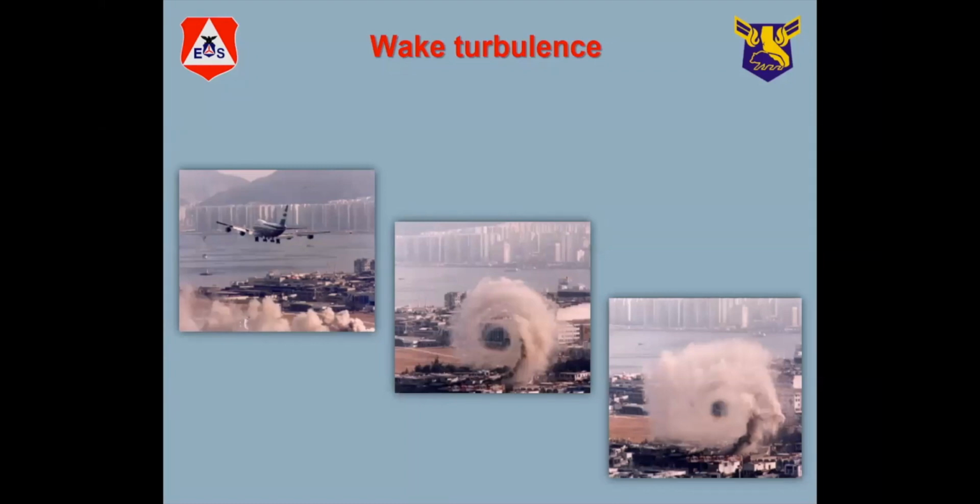I'll just add that one of the most severe wake turbulence actually comes from hover taxiing helicopters. And so we have certain criteria as far as spacing behind other aircraft. But if there's a helicopter out there on a taxiway or anywhere near you, you need to be at least 500 feet away from that thing, because it's a tremendous amount of wake turbulence off those rotors.